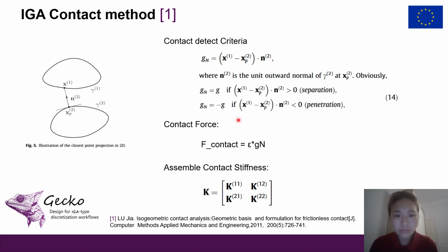So here, the extra stiffness matrix proportional to the penalty factor acts like a spring between the two bodies. In this way, the contact constraint is approximately enforced, while still allowing a small controllable penetration for numerical stability.